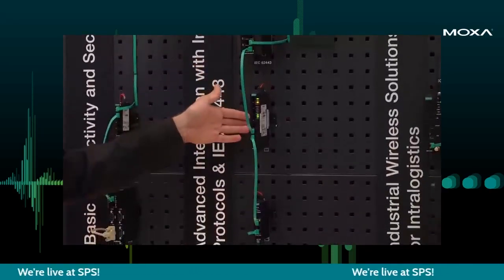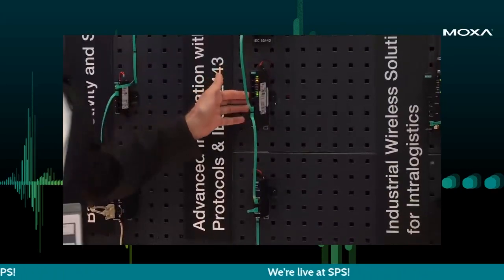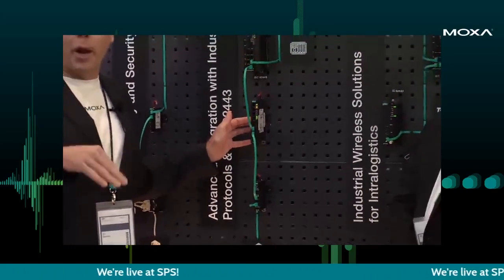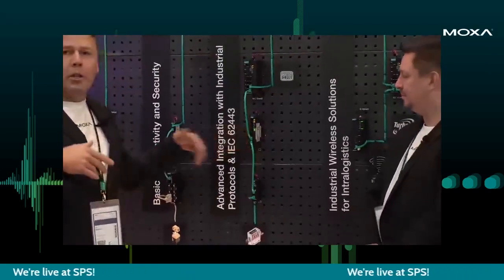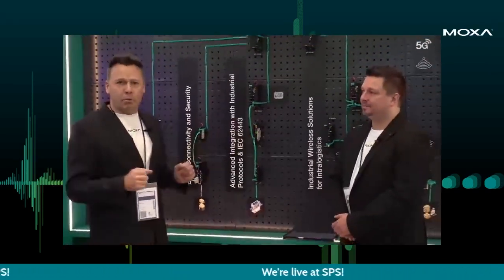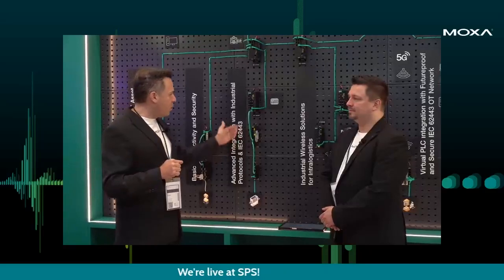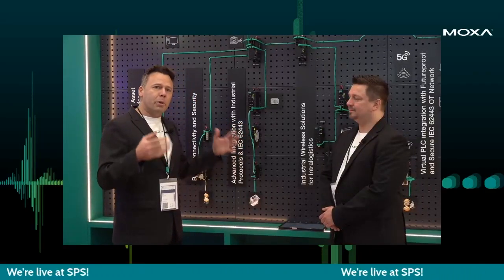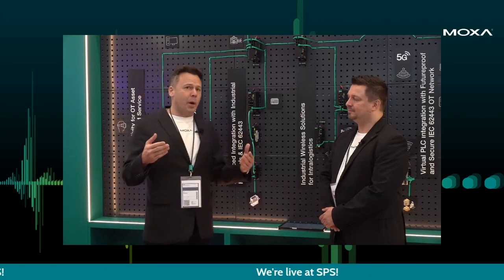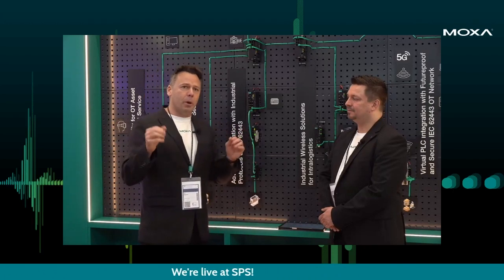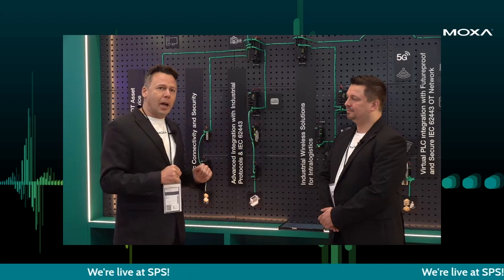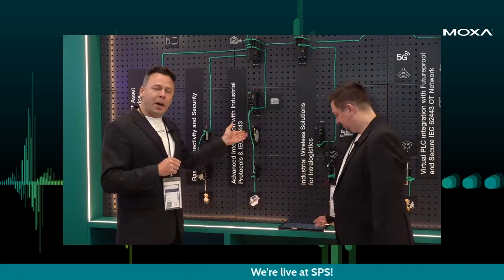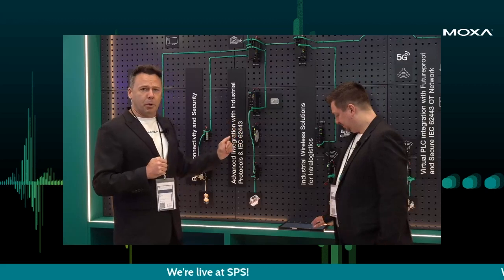This device also has a very nice graphic user interface with multiple languages: English, Chinese, French, Japanese, German. So it is applicable to work in any part of the world. The beauty of this device, it supports redundancy on the power input, but not only on the power input, redundancy in the protocols. Rapid spanning tree protocol, which is highly desirable to prevent network failures and for unmanned recovery of the network. Then spanning tree protocol, media redundancy protocol.